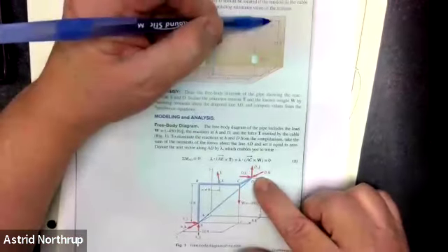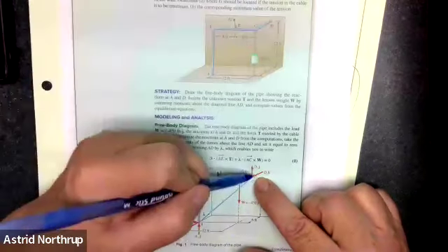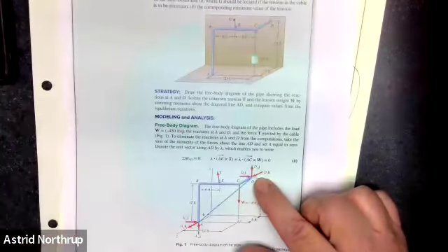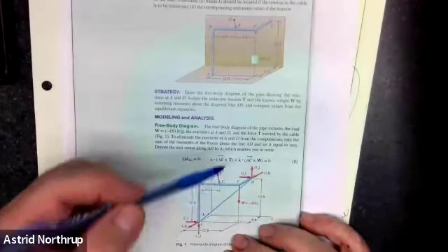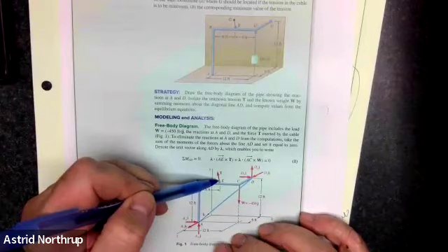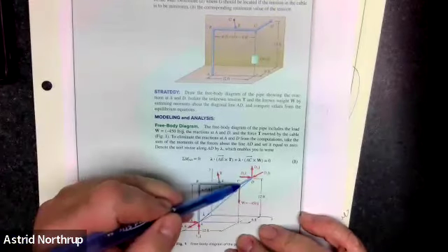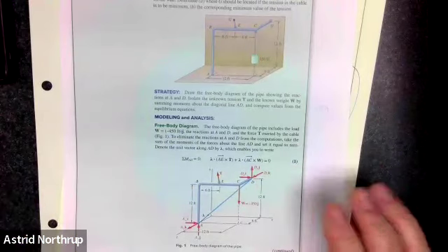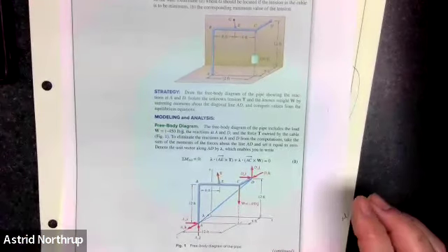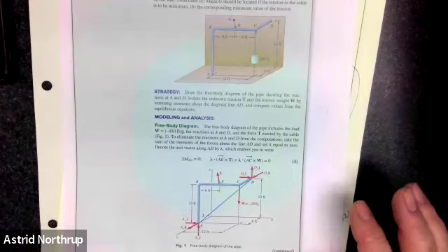And then here at D, we have a fixed support, positive, positive, positive. So the way this is drawn, we have 3, this is going to have 2 components, right? 4, 5, 6, 7, 8, 9 unknowns, essentially. So something's got to give.